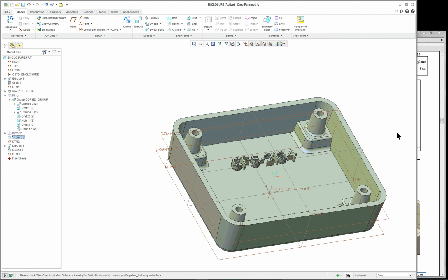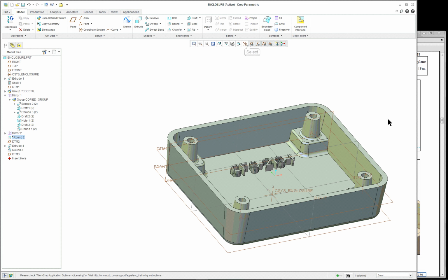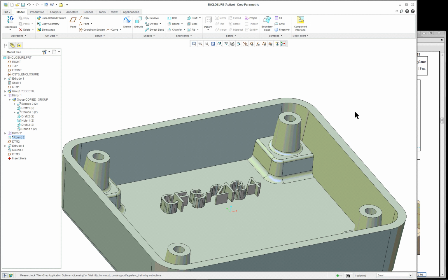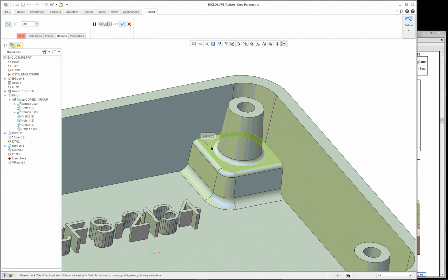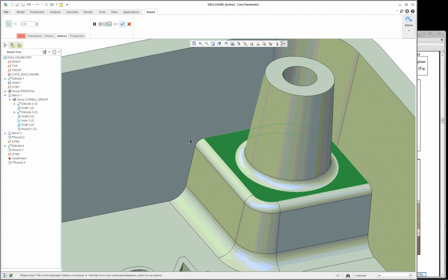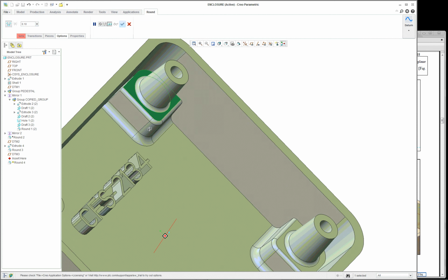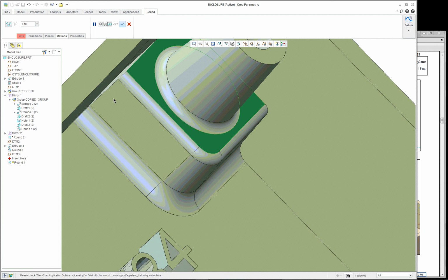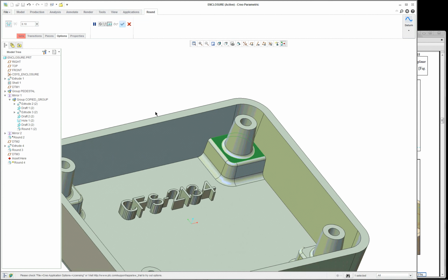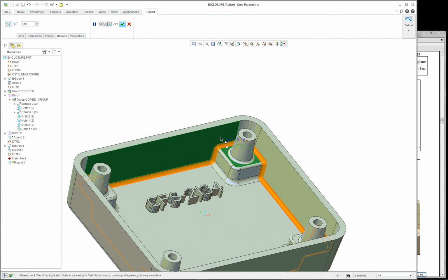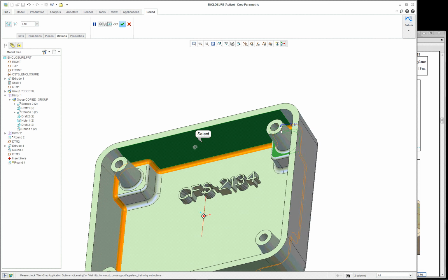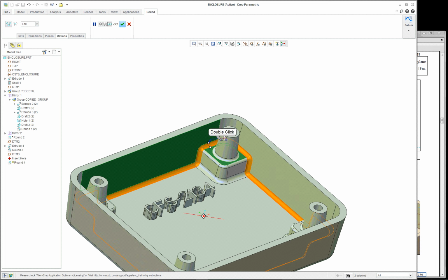Basically what we're doing now is you're going to put in a round, and maybe we'll turn off our datum features to unclutter the view. And in this case, you can select the round first, and you're going to pick the surface, not the edge. Remember, there's no edge here. See the gap? Hold down the control key and pick the other one. And it should preview all the way around. If it doesn't, again, your dimensions are slightly off. Go back and check every feature.